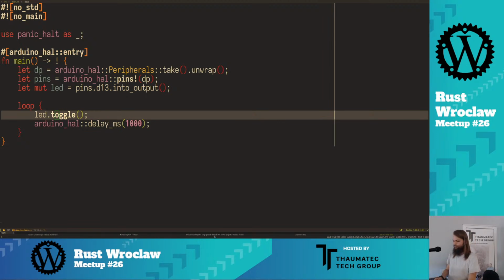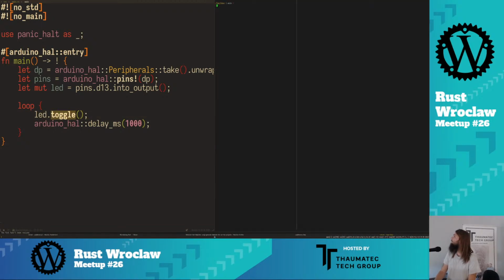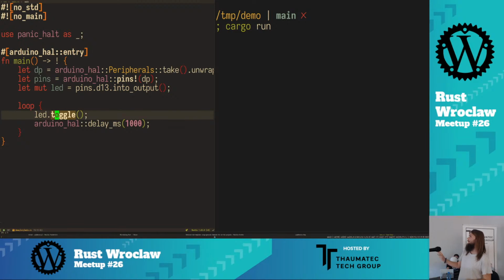And to flash it, I will also open the terminal right here. Zoom in a bit. Flash it with the template I've cloned. The flashing really boils down to running cargo run. Some Rust programmers might not be aware of why this will work instead of running the code locally. Because in Cargo.toml you can specify a different command for what should happen when you run cargo run. In this case, the template we are using just aliases cargo run to flash to this AVR, so that it's easier to use.